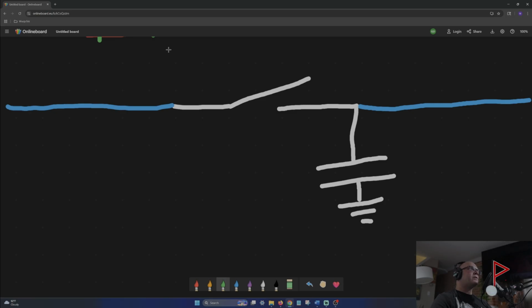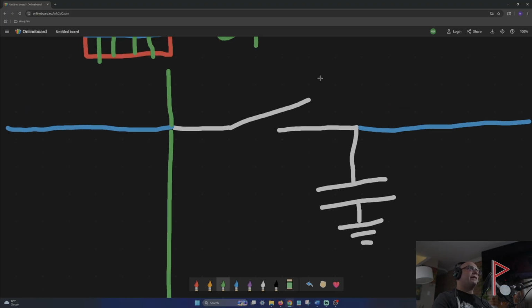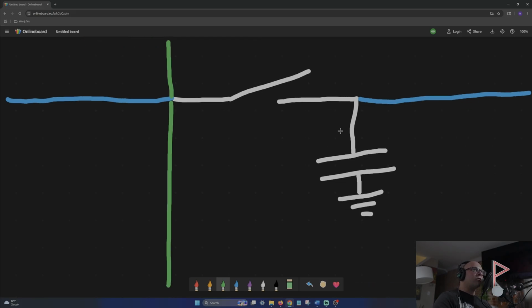And your bit lines are going vertically. When a row is asserted, when a word line is asserted, all of the capacitors are read on that specific word line. It can't read all of the capacitors, because then you'd have voltage going into your bit line, colliding with the transistors and capacitors up here, and voltages colliding across your bit line. So only the capacitors associated with that word line that is being asserted are being read.